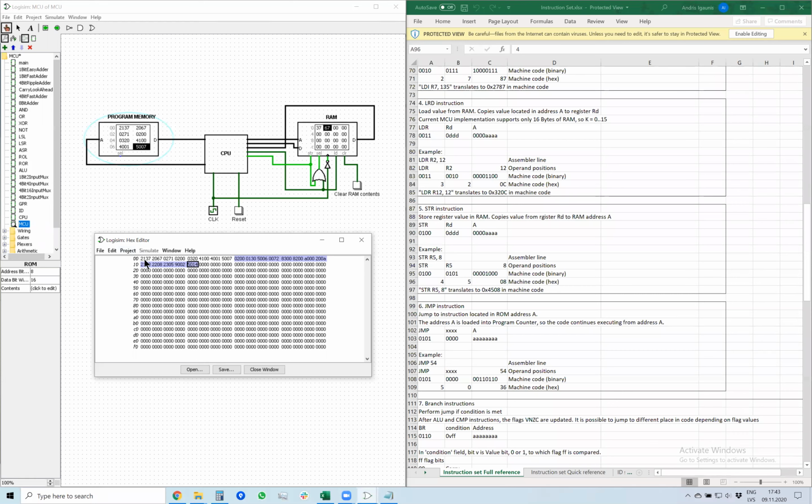So when you write a code, you flash it and it's written into the program memory. If you write a new code, only the part where the new code exists is written. And if it's shorter than the previous code, then some parts of the old code still stay inside the flash memory at the end, because we shouldn't erase the flash memory uselessly.